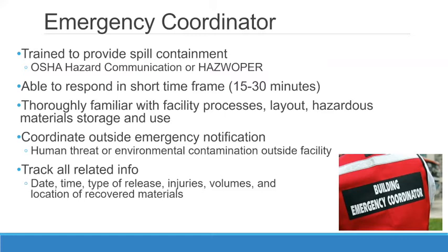The emergency coordinator needs to respond within a short time frame, 15 to 30 minutes. Typically, in the smaller operations, it's going to be someone of higher responsibility. It could even be the owner of the company that's going to be the coordinator. You need to be thoroughly familiar with the facility, the process, the layout, the hazards, where the material is stored, and then coordinate with any outside emergency notification in case there is a spill or release.